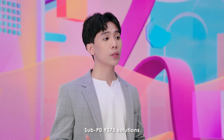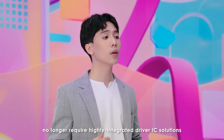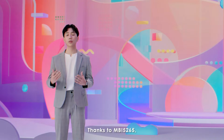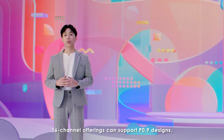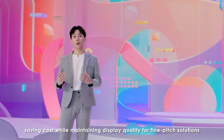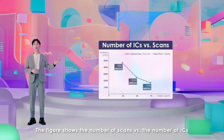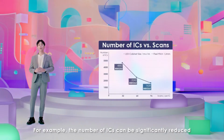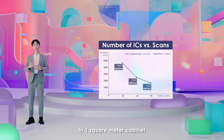Sub P0.9375 solutions no longer require highly integrated driver IC solutions. Thanks to MBI5265, 16-channel offerings can support P0.9 designs, saving cost while maintaining display quality for fine-pitch solutions. The figure shows the number of scans versus the number of ICs. For example, the number of ICs can be significantly reduced as the number of scans increases with 16-channel driver ICs in 1 square meter cabinet.